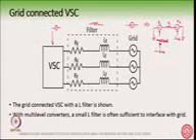So when you have these two sine waves, the power exchange and the current exchange is controlled by the X, the filter in between. You can have other types of filters also, but for these multi-level converters, a small X which interfaces with the grid is sufficient.